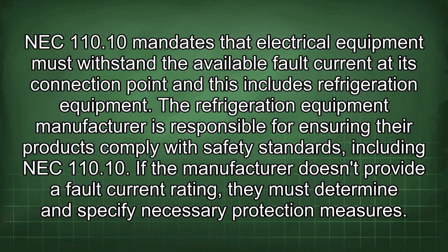NEC 110.10 mandates that electrical equipment must withstand the available fault current at its connection point, and this includes refrigeration equipment. The refrigeration equipment manufacturer is responsible for ensuring their products comply with safety standards, including NEC 110.10. If the manufacturer doesn't provide a fault current rating, they must determine and specify necessary protection measures.